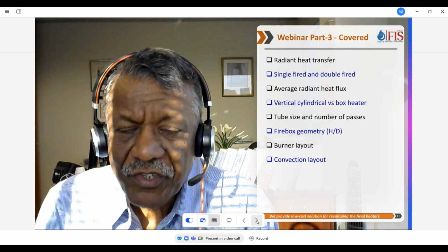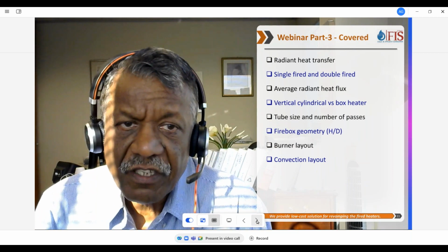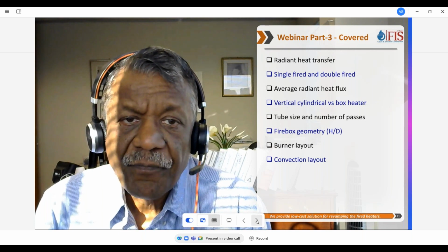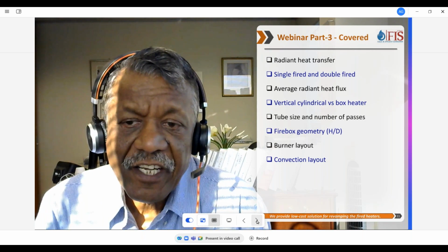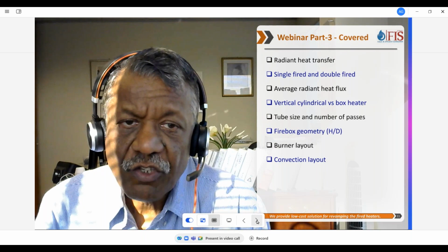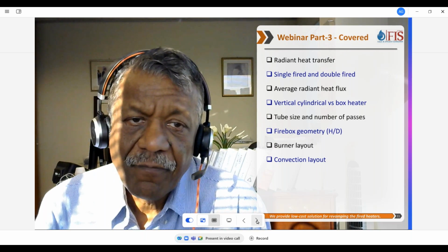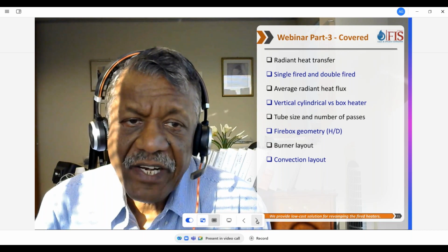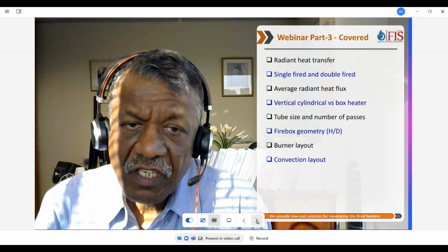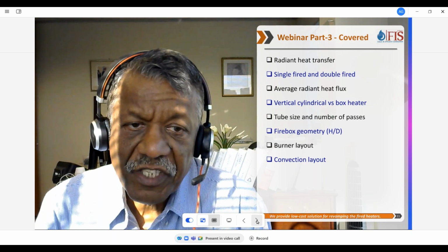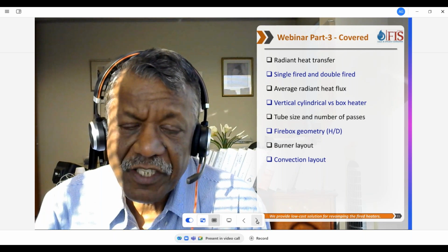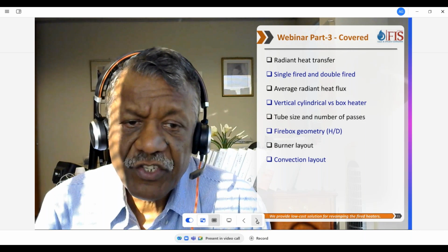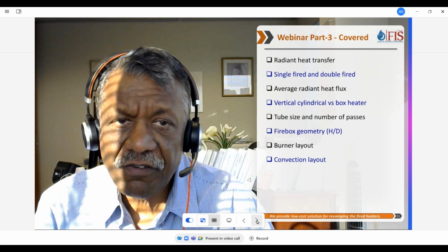And then in the third webinar, which was last month, we talked about radiant heat transfer. What are the different arrangements of tubes? There are tubes which are single fired, double fired. And then we covered the importance of radiant heat flux, vertical cylindrical versus box heaters, tube size, number of passes, firebox geometry, burner layout, and convection layout. So we did all this in our third webinar.